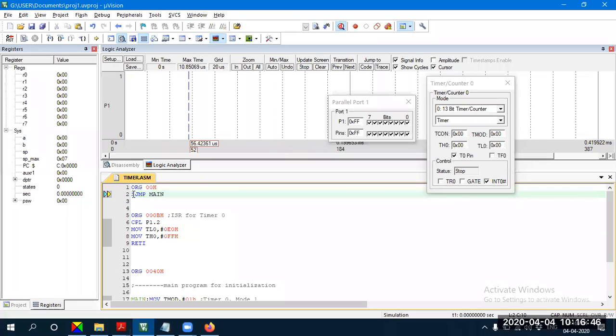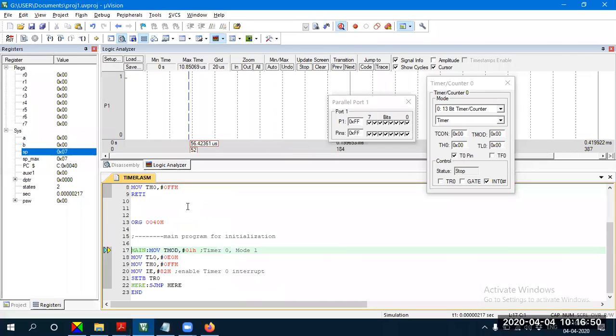So thereby, the microcontroller starts with this instruction. It will take a jump to the main program. Guys, could you see the control transfer? It transferred from the LJMP instruction to the main instruction, loaded at address 48. And it will execute the main program. Meantime, when this line is executed,